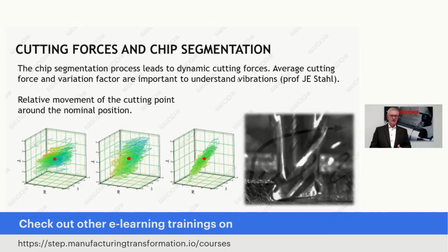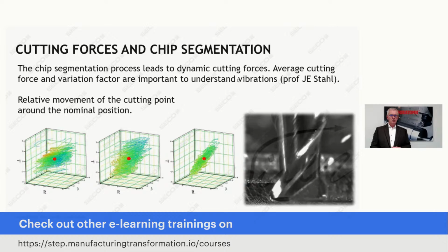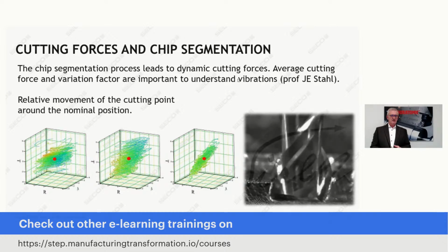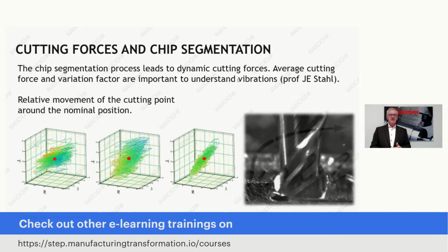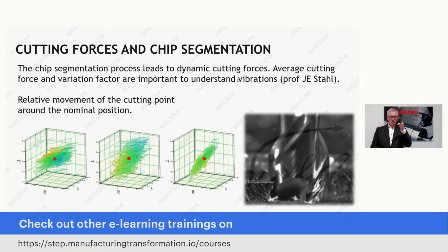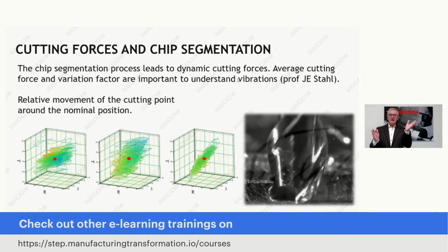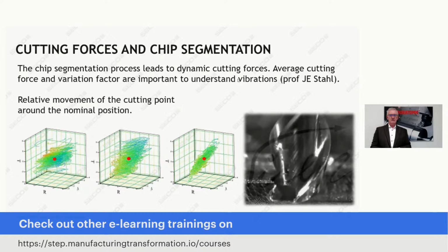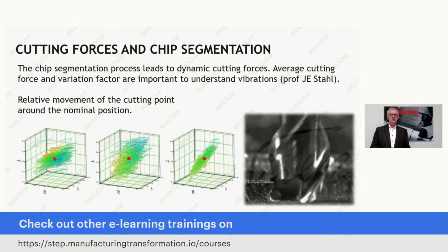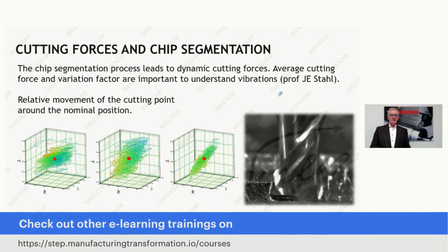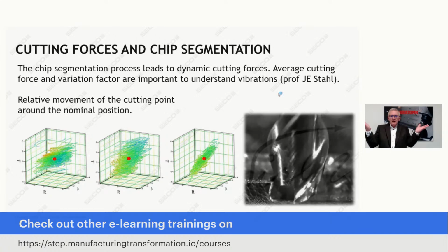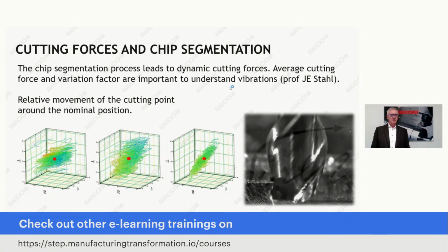And the proof of it you see here on the movie. It's a solid carbide milling cutter. It's an end mill, and you see the movement. We talk about microns. Let's take the correct scale here. We talk about microns, but there is movement, so there are vibrations.